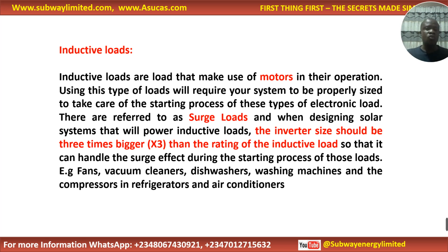So what are inductive loads? Those are loads that consist of motors. They consume lots of power during the startup process. Let's take a closer look at inductive loads. Inductive loads make use of motors in their operation, like your fridge, like your photocopying machine. When they start up, they consume lots of power, and it is advisable that you design the inverter size at 3 times the power rating of the inductive load.